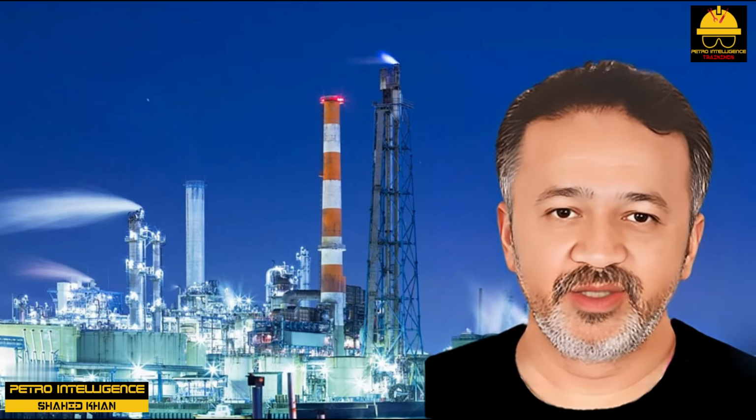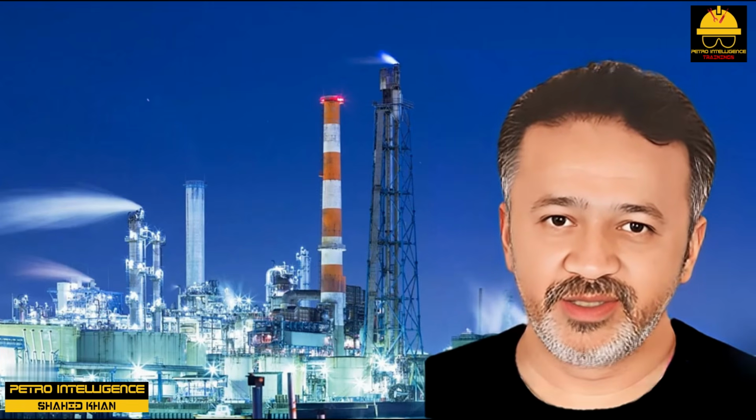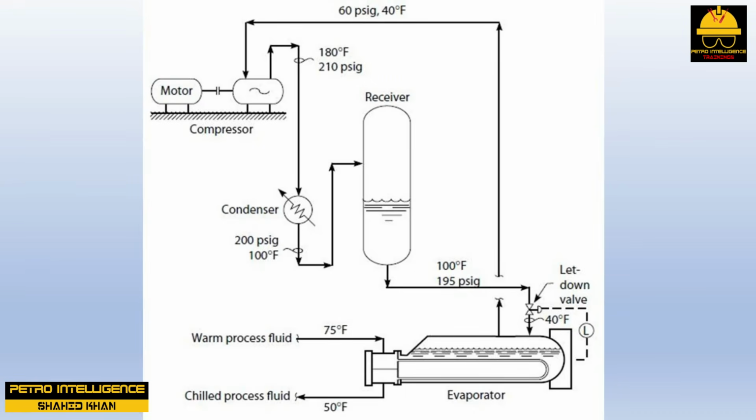The trick is to make the refrigerant lighter or more volatile. A lighter refrigerant will allow the evaporator, shown in picture, to operate at a higher pressure and/or a lower temperature. Increasing the suction pressure increases the density of the refrigerant vapor flowing to the compressor. Even though the volume of gas flow is constant, the weight flow of the circulating refrigerant can be increased. Yes, we can get 6 pounds of manure in a 5-pound bag if we make the manure denser.